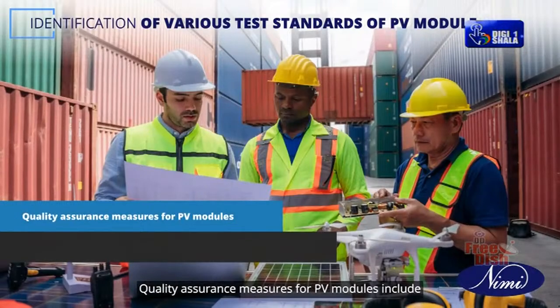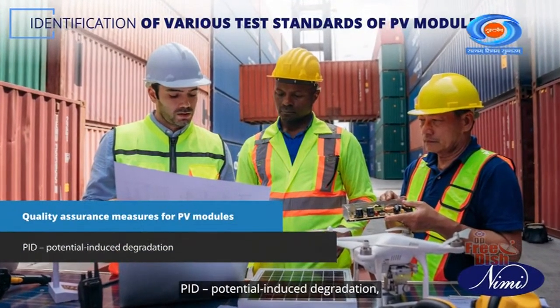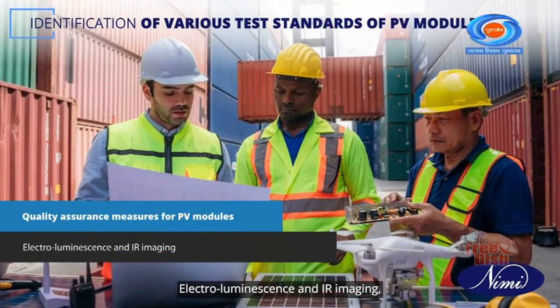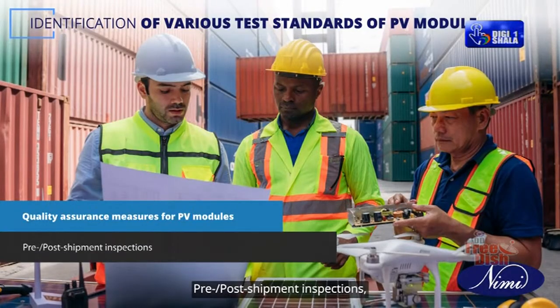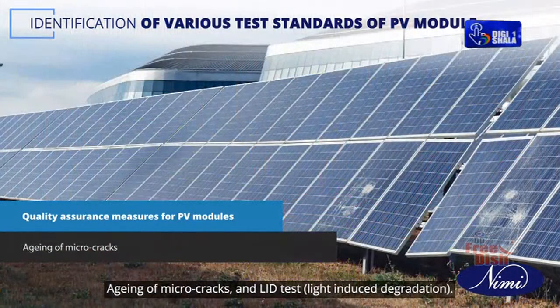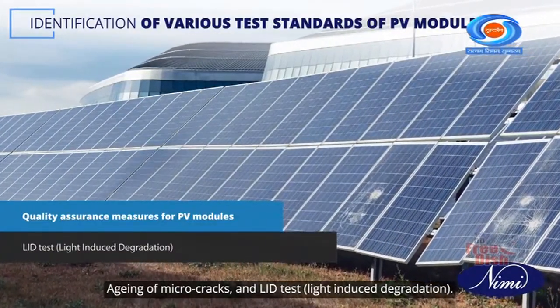Quality assurance measures for PV modules include PID, Potential Induced Degradation, electroluminescence and IR imaging, pre or post shipment inspections, aging of micro cracks, and LID test, light induced degradation.